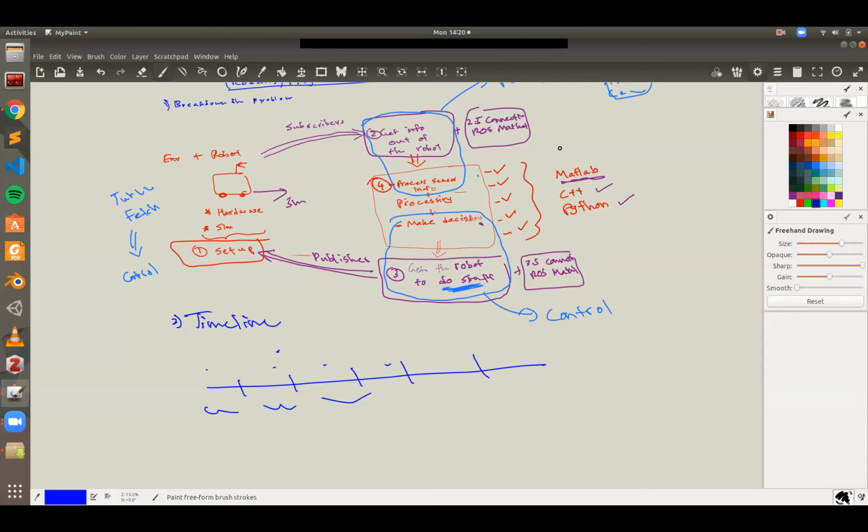It depends on your project, right? If your project is like 2 TurtleBots following each other, then you don't necessarily have to use Gazebo. You can do it in RViz. But for example, if it's a grasping situation where you're trying to detect an object and grasp it, you will have to use Gazebo. Because there's a perception element to this, because you have to sense things and detect things, I think you'll have to use Gazebo, right?